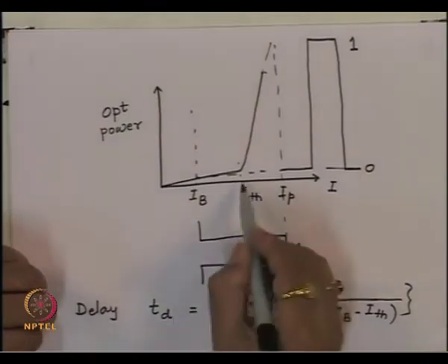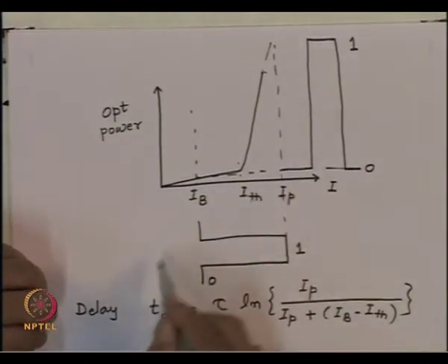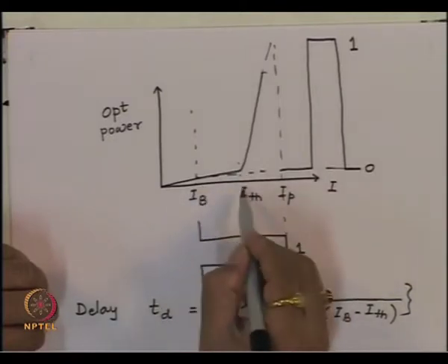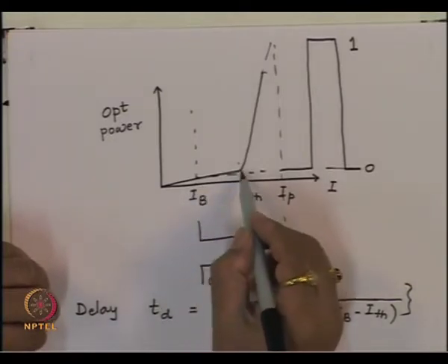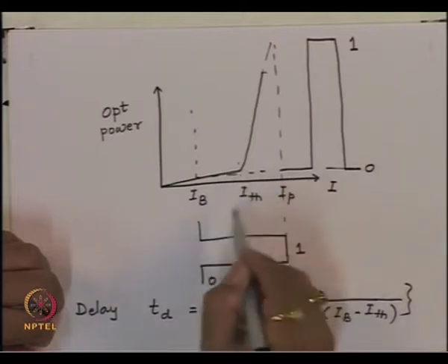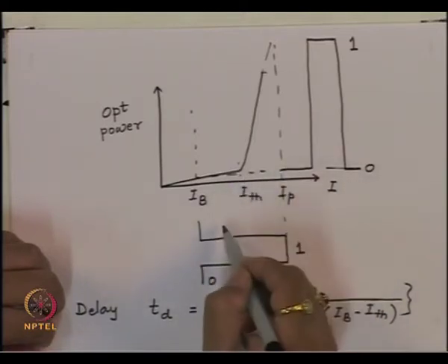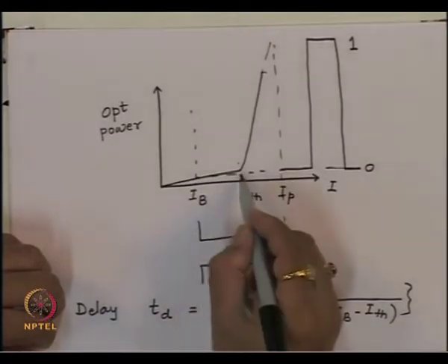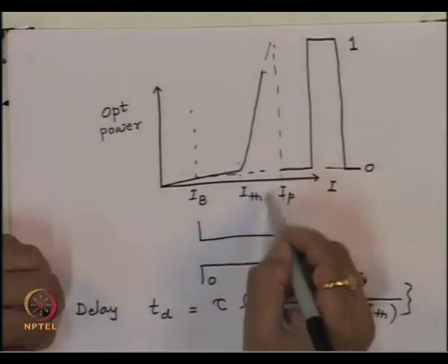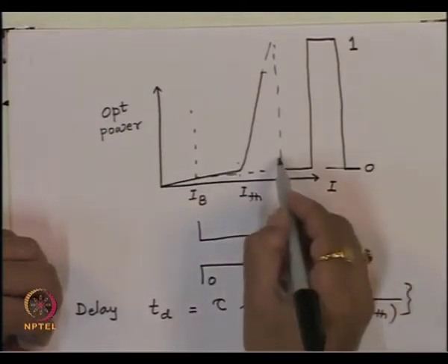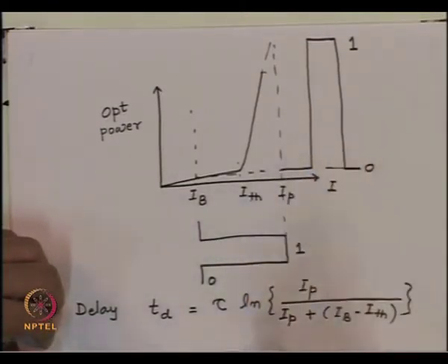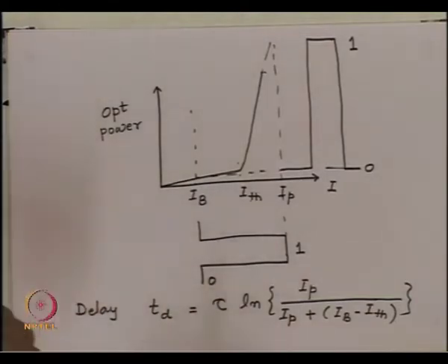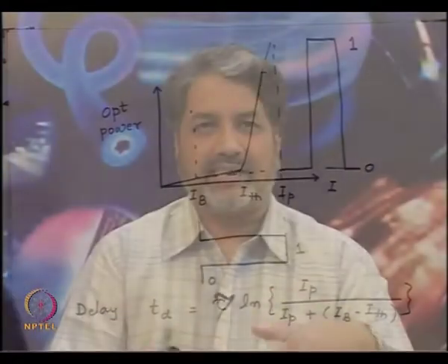In the first situation, if we track the threshold current, you will see that if we put the biasing current here and temperature increases, the threshold current will increase. If I increase the biasing current again to come to threshold current, we will be essentially pumping more current into the junction, which will increase the temperature still further, which will drift the threshold current still further, and so on. So, you will have some kind of a positive mechanism here, which is not very desirable, because then the junction will get overheated and your laser will get damaged.